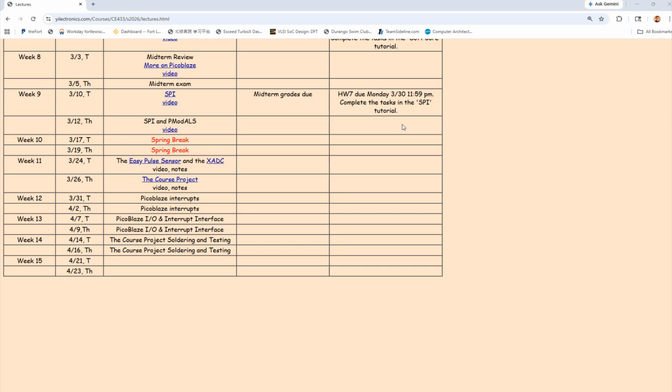So only the AC signal, which carries the information, is left and goes to the next stage, and usually it's a low pass filter, right? And then you amplify it, but at the same time you need to lift the signal to a certain DC bias, because your power rails are not positive and negative voltages, not dual power supply. It's usually just a VCC and ground. So you need to lift it to the middle of the power rails, so it's able to swing and occupy as much dynamic range of the power rail as possible, and then you digitize it.